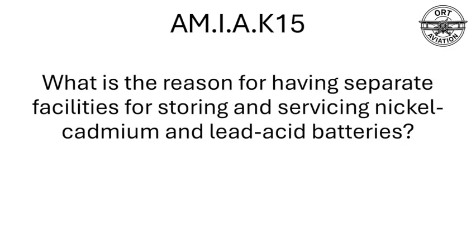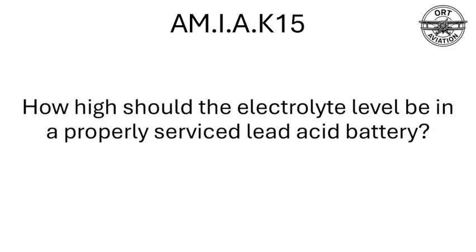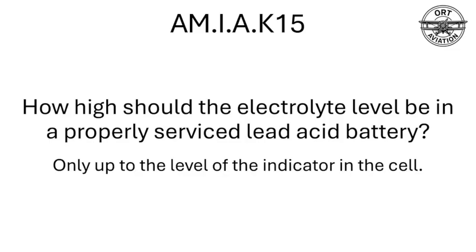What is the reason for having a separate facility for storing and servicing nickel cadmium and lead-acid batteries? The electrolyte in the two types of batteries is chemically opposite, and the fumes from one type can contaminate the electrolyte of the other type. How high should the electrolyte level be in a properly serviced lead-acid battery? Only up to the level of the indicator in the cell.